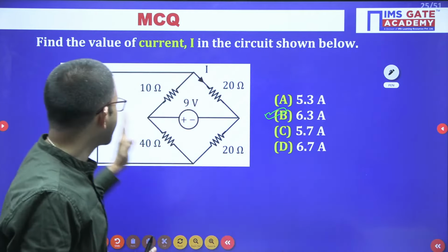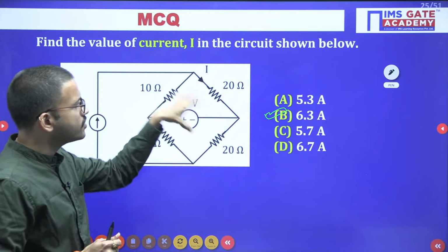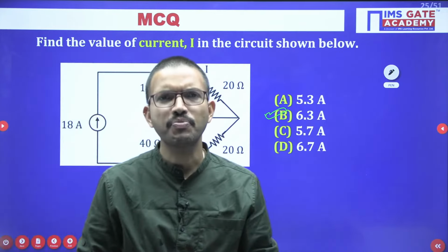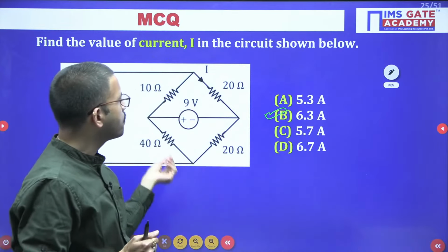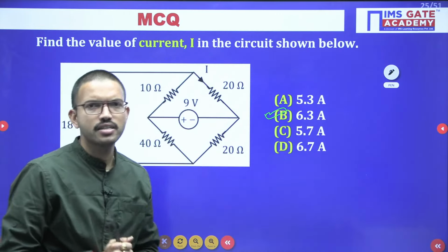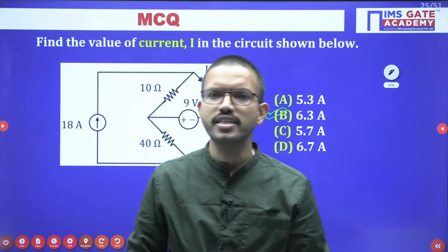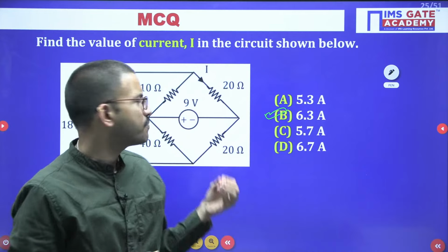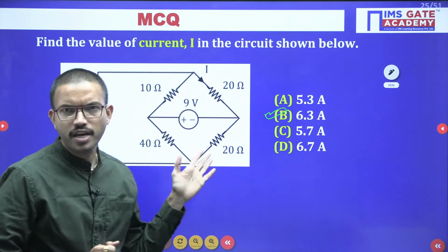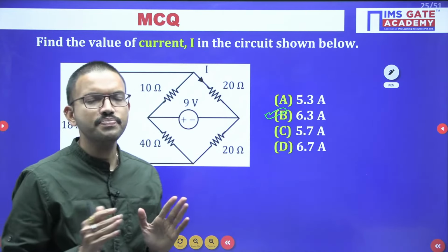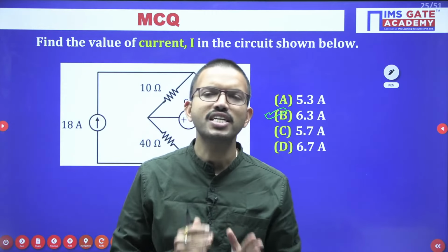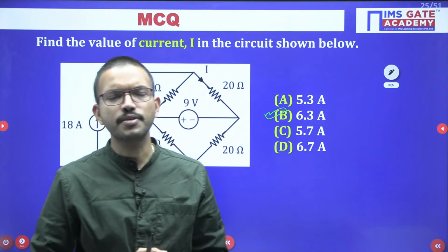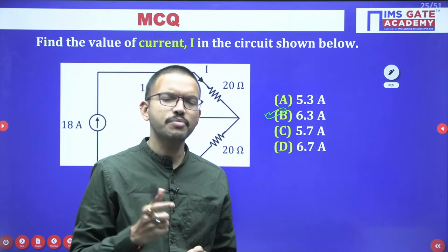Since you are considering only one source at a time, the rest of the circuit you may get in the combination of series connection or parallel connection, etc., or simple nodal, whatever the basic concepts, methods or laws that you have studied in the first chapter. With the help of any of those, based on the possibility, you can apply them. So whenever a given circuit or network has multiple sources present, wherever you can easily solve with the superposition theorem, that time you can apply it.